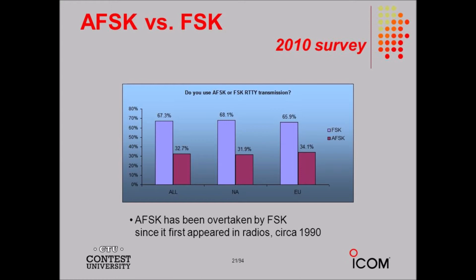During the early 20th century, communications engineers perfected a way to modify AM signals in this way. They called the resulting mode single sideband, a term which endures to this day. When we remove the carrier and one of these sidebands from an AM signal, the remaining energy has a spectral display resembling figure 25.4. In this case, we eliminate the upper sideband along with the carrier, leaving only the lower sideband. We could just as well remove the lower sideband along with the carrier, leaving only the upper sideband.